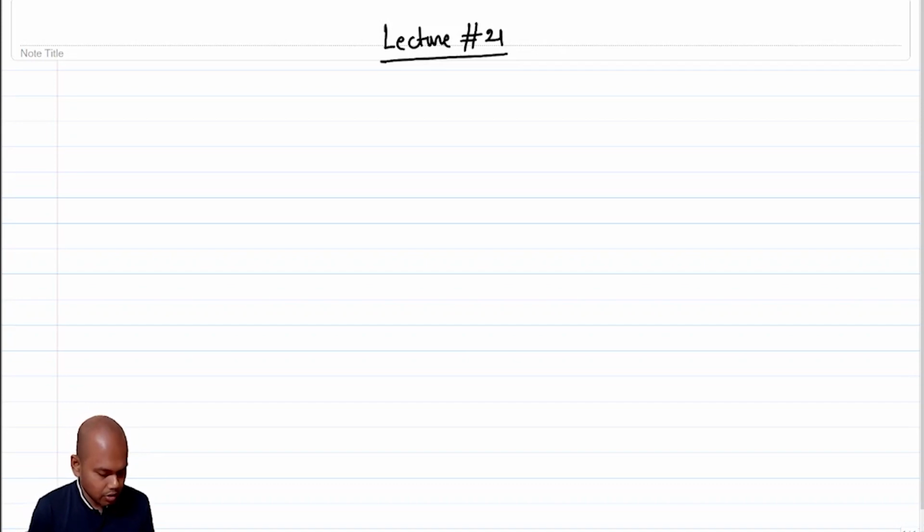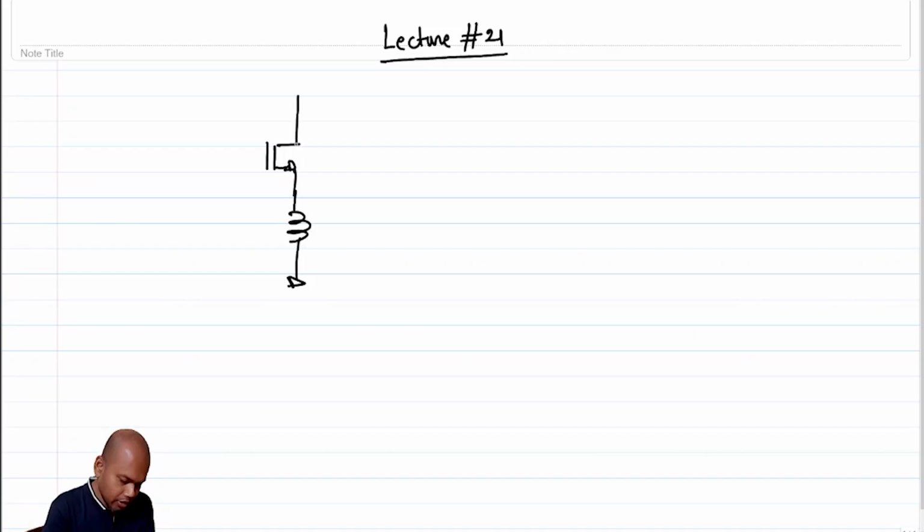In the last lecture, we saw how to not use noisy elements, but yet be able to generate a real impedance, and use it for matching. The supposed benefit is, if I am not using an explicit resistor or a transistor to get the final matching, then I should be able to benefit from low noise figure. That's the supposed assumption. And with that in mind, we came up with this architecture. It's a low noise amplifier where we are only concentrating on matching right now,